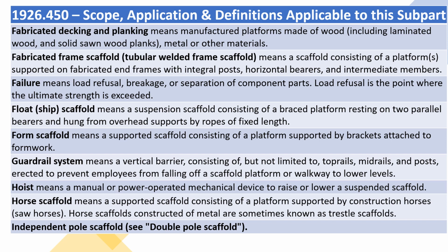Float, ship, scaffold means a suspension scaffold consisting of a braced platform resting on two parallel bearers and hung from overhead supports by ropes of fixed length. Form scaffold means a supported scaffold consisting of a platform supported by brackets attached to formwork. Guardrail system means a vertical barrier consisting of, but not limited to, top rails, mid rails, and posts erected to prevent employees from falling off a scaffold platform or walkway to lower levels. Hoist means a manual or power-operated mechanical device to raise or lower a suspended scaffold. Horse scaffold means a supported scaffold consisting of a platform supported by construction horses, sawhorses.